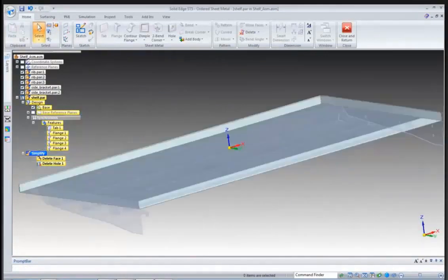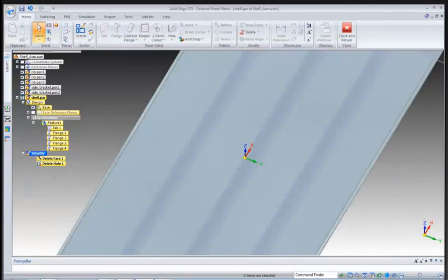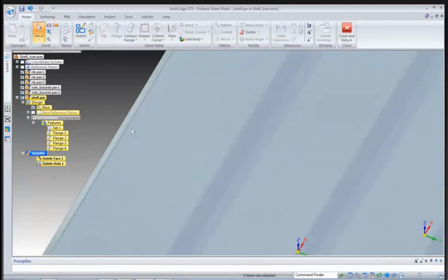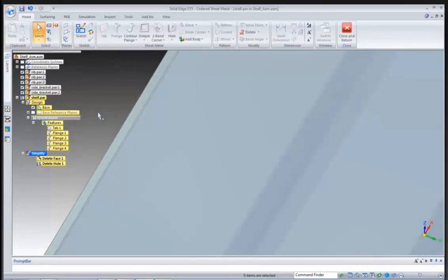Now the other thing I want to do, and I zoom in here, you can see the thickness. This is a sheet metal part. It's a 16 gauge stainless steel, so it's about 1.5 millimeters. And when I was talking about having a lot of elements, it's the same thing going through the thickness here. If I had to use a tetrahedral element, since they have degrees of freedom that are only translational, meaning only x, y, and z displacement, I don't have the rotational degrees of freedom. If I want to capture the bending, I have to get 2 or 3 through the thickness.